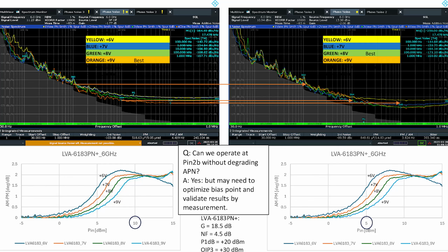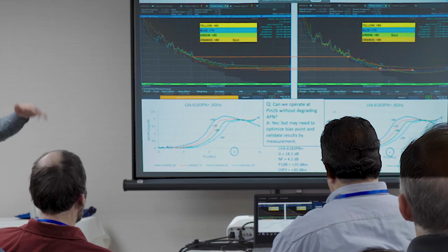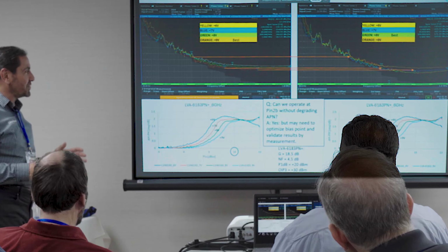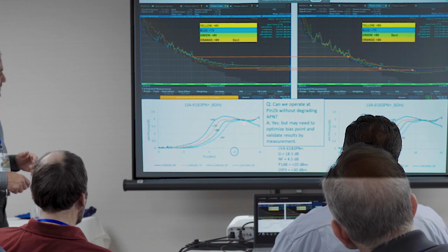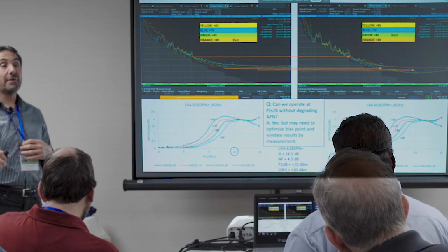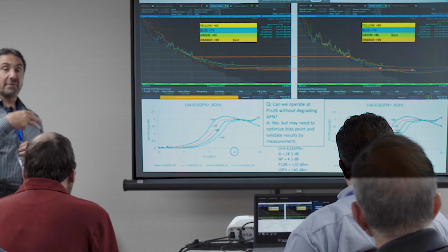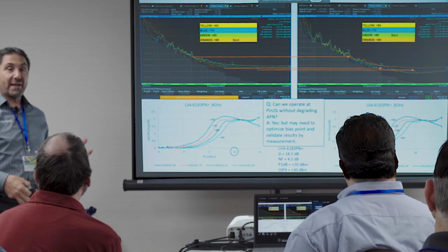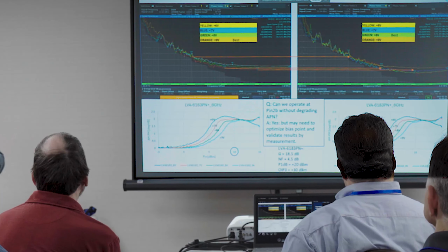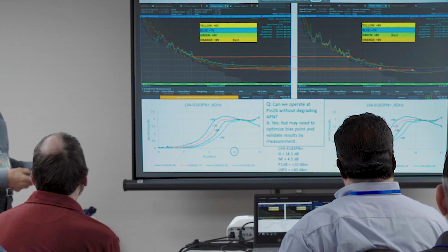Then there was that third region, if you recall. What if we operate in that really, really highly saturated region? Because that's another rule of thumb. Oh, just operate it saturated, you'll be fine. Well, not really. This part, notice, does not get significantly better in that region, where the other part we looked at came way down. So again, there's no general rule that says if you run saturated, you will be better by default. That's not the case. We just demonstrated it here by example.